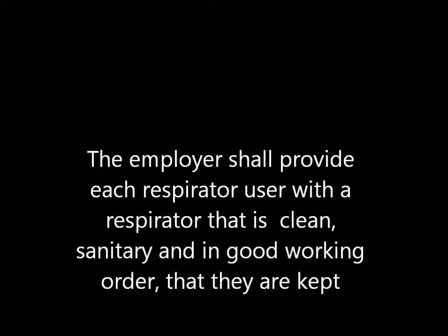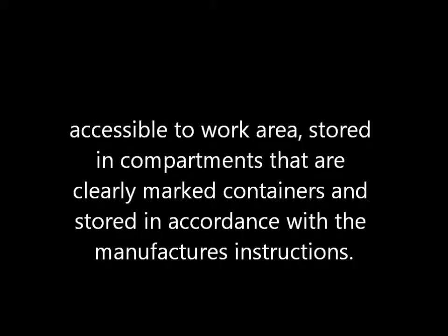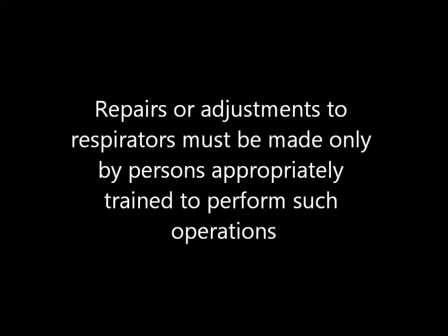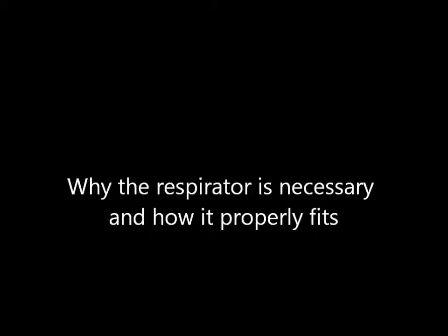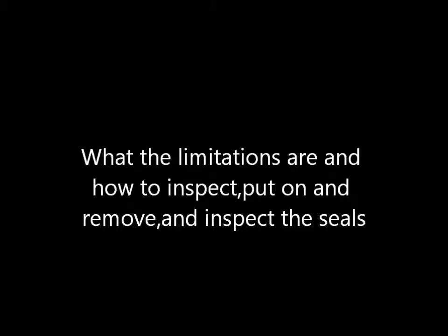The employer shall provide each respirator user with a respirator that is clean, sanitary, and in good working order, kept accessible to the work area, and stored in clearly marked compartments or containers in accordance with the manufacturer's instructions. Repairs or adjustments to respirators will be made only by persons appropriately trained to perform such operations. Employers shall ensure that each employee demonstrates knowledge of at least the following: why the respirator is necessary and how it properly fits, what the limitations are, and how to inspect, put on, and remove it, and inspect the seals.